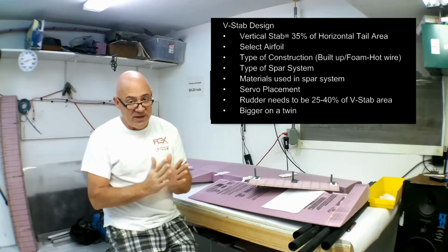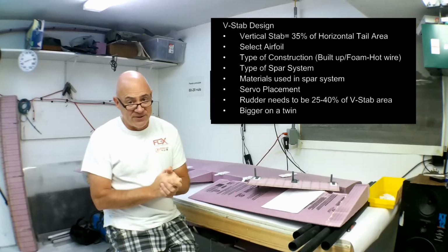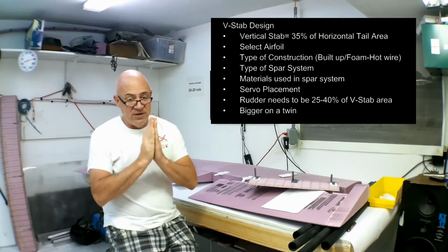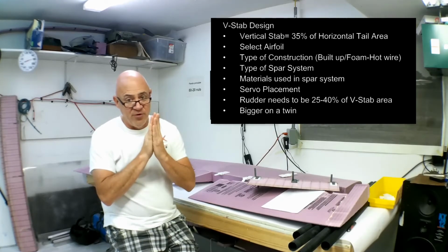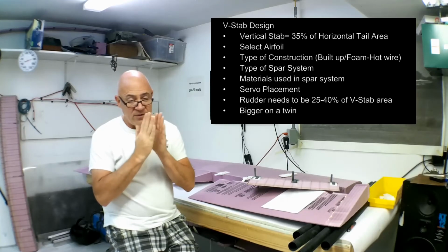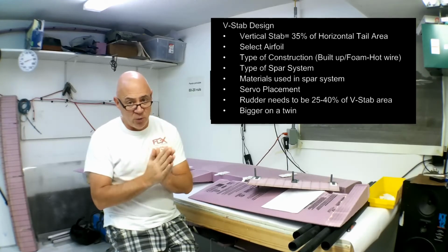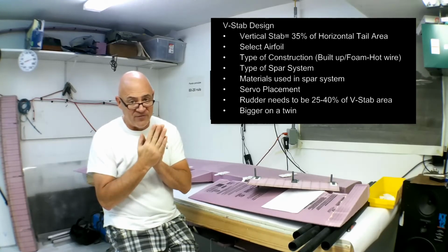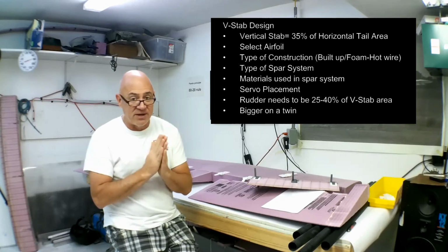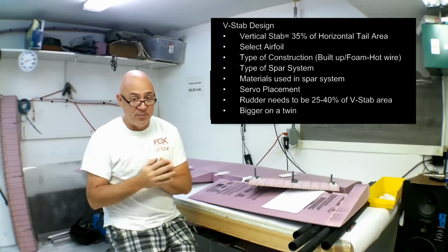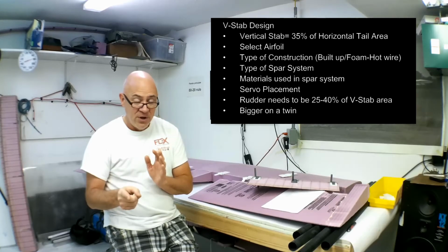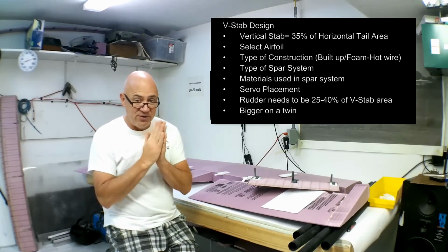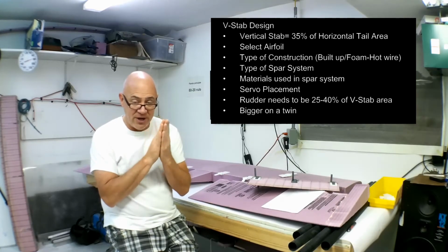There's been a couple of big twins that have crashed in the last 10 years. Each of them looked like they had 15 degrees of movement in the rudder. There's no point in having a rudder on a twin if you're not going to get 35 or 40 degrees of movement and expect to have enough rudder to steer the airplane if you lose an engine. Look at how much deflection you see on a real multi-engine airplane, how much that rudder moves.